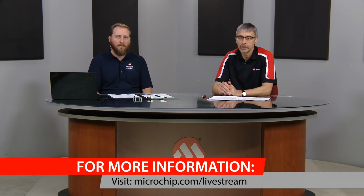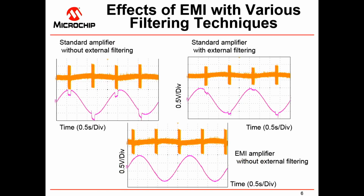Right. And to extend on this a little bit further, we've prepared a slide here to visually show again the effects of EMI as it occurs under various conditions. It's a bit of a busy slide, but I'll walk you through it. I'm starting in the upper left-hand corner, which is labeled standard amplifier without external filtering. The orange trace is our RF signal. It's pulsed to make its effects more visible, and it's simply riding on noise. If I recall correctly, it's an 800 megahertz pulsed RF.